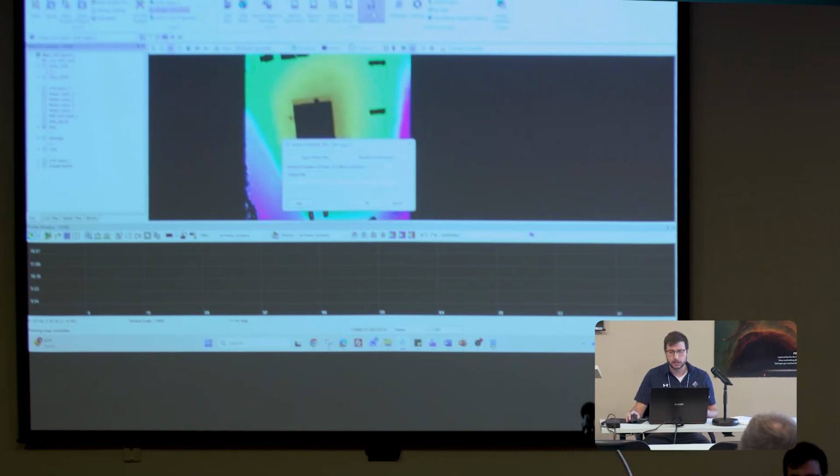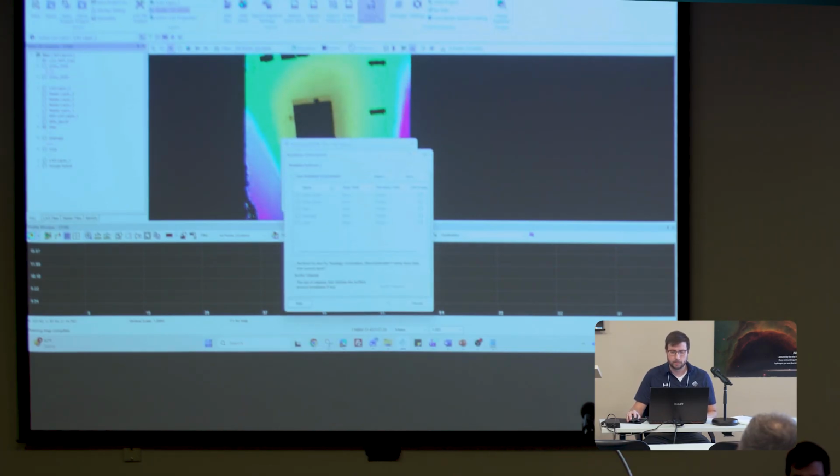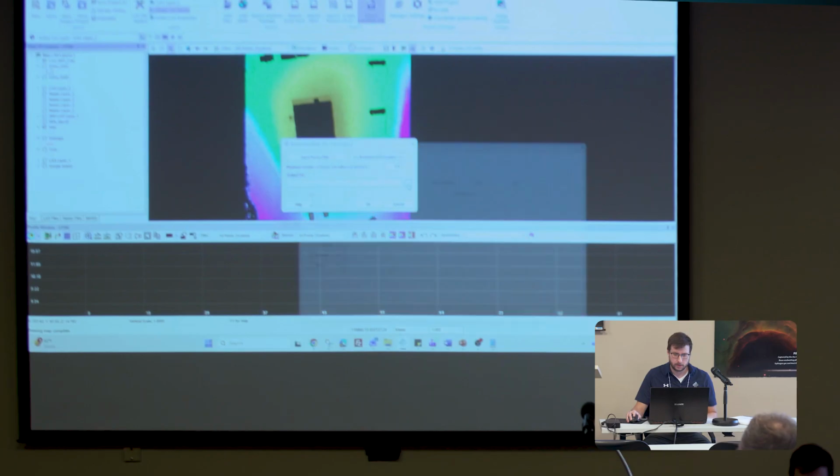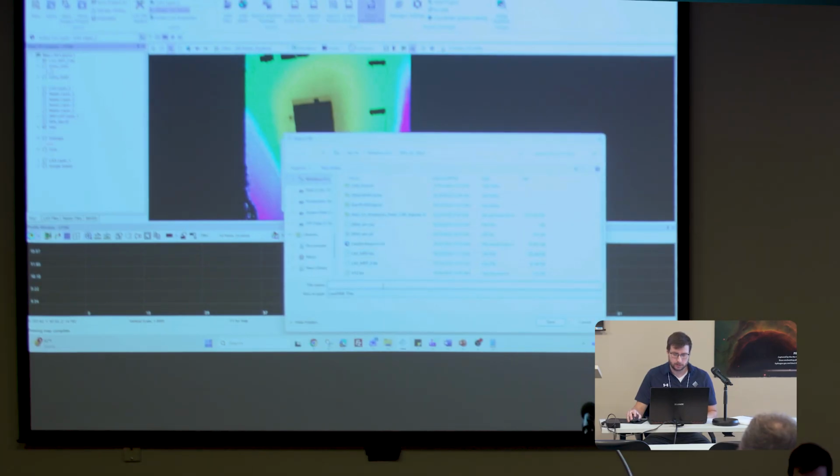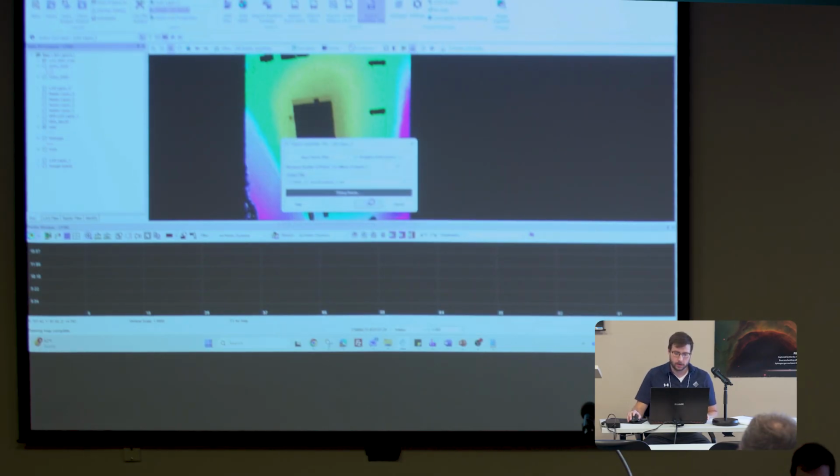So I'm going to go through the settings again. Turn my break line on. I'll turn on perform on-the-fly topology corrections. I'll set an output location. Just call it LandXML 2. Save. Hit OK. See if it does any better. Oh, I referenced the LAS layer 2, so it's probably going to break in the same way. Let's see.